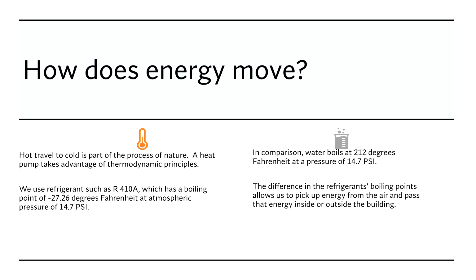The ability of refrigerants to boil off, or in the terms of refrigeration systems, we talk about evaporating, turning from a liquid to a vapor, is what allows us to pick up the heat and move it from one place to another. Okay, and that is the beauty of a refrigeration system, and that is the heart of the thermodynamic principles of a heat pump.